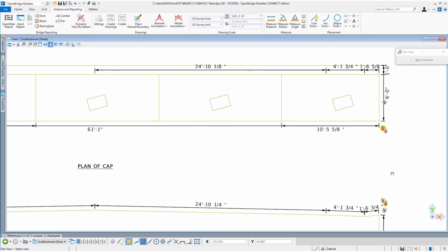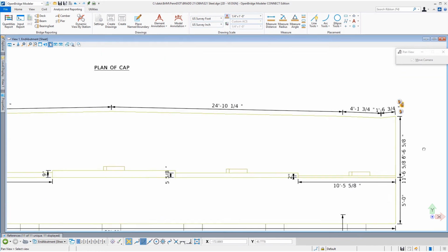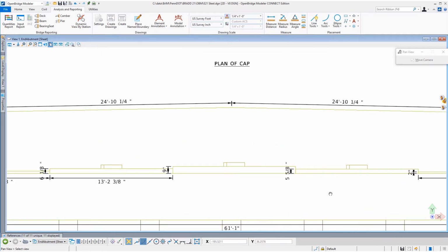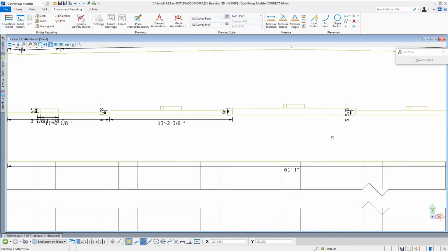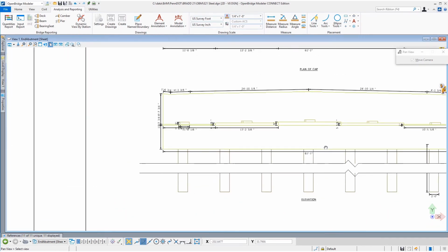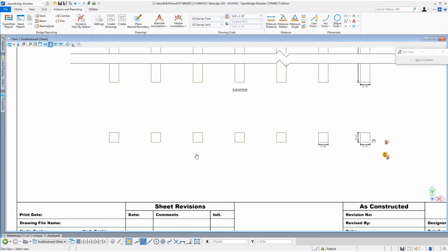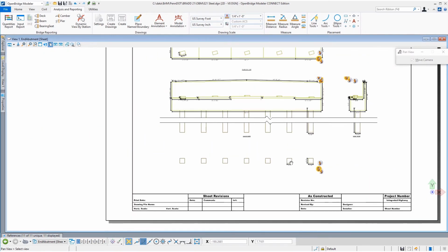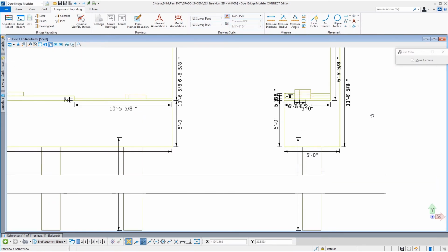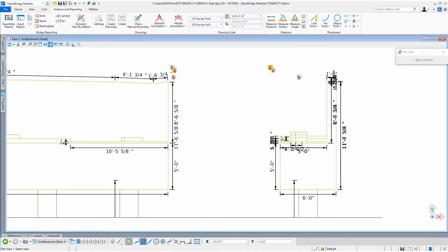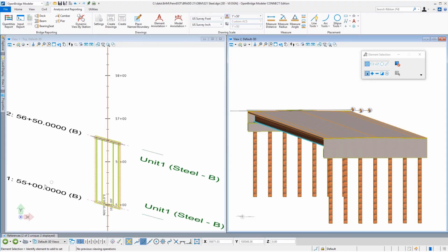It's just a matter of you defining the sheet first, right? You have to set it up, and also play with the dimension styles to see which ones you don't want to do, how you want to cut. For example, here the piers are too deep, so they do not fit on the file itself, so I can put cut lines there automatically. So this will be the full proper setup of a sheet. And it's all reference again, right? So you can do all of that.